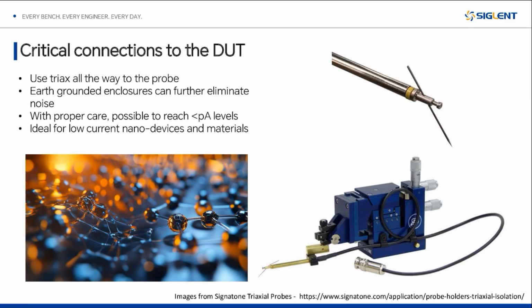It's a really great way to get your picoamp level measurements when needed, with a little bit of extra care on your cabling side, moving up from BNCs or shielded bananas up to a triax guarded configuration.